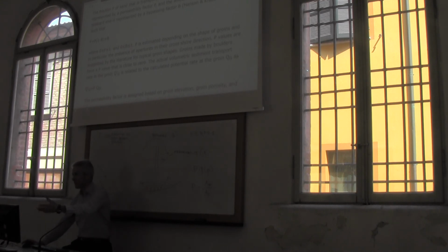But okay, this is a standard function. Yes, because then it's the fraction of the sand that is transported over the groin. So in the case that all the sand is transported over the groin, the summation of B and P should be equal to 1 maybe. And if not 100% of the sand is transported, the summation shouldn't be equal to 1.